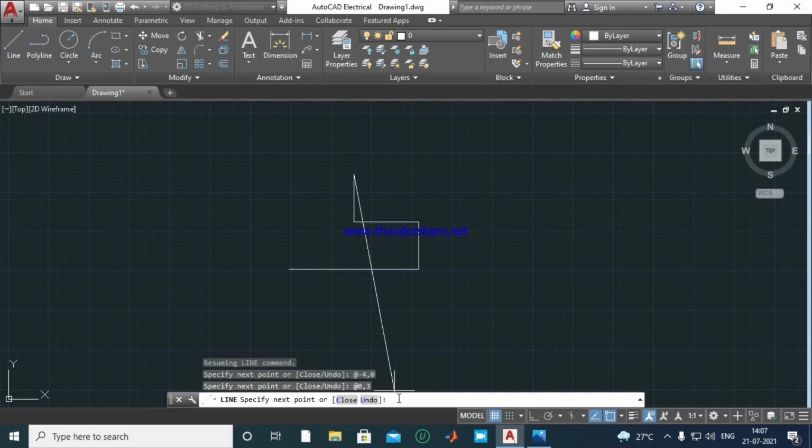Okay, now again I am using @ sign. We are going in backward direction. We are saying that this point is origin because we have used @ sign. So that means this x and y are 0 here, and the line is going to be drawn in x direction in backward direction. So previous value is 0, new value is 4, right? So I will give -4. Okay, because 0 minus 4 is -4, comma y value will be 0, right?